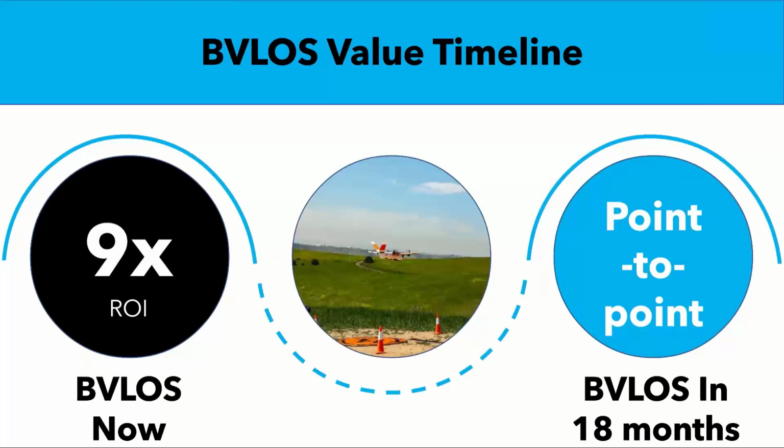The radius that's being approved for BVLOS now is considered a low risk application attempt of a 3 mile radius, with the aircraft operating beyond that a little bit more. So you have a VO at the 3 mile mark and the aircraft actually flies beyond that furthest VO. That radius is only getting greater, ultimately leading ourselves into point-to-point operations. So single launch point, you're talking about a 9x coverage per flight.